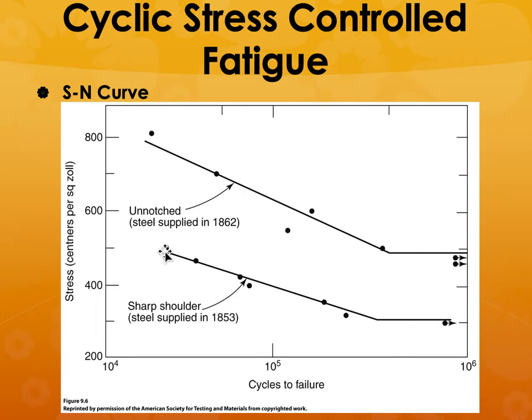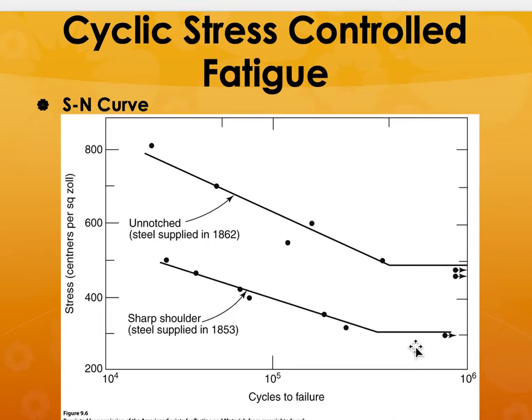But suppose you had no notches, then how many cycles can it withstand? Probably unlimited life. So the effect of the notch and the sharp stress concentrations can be pretty substantial. So please understand that, okay?